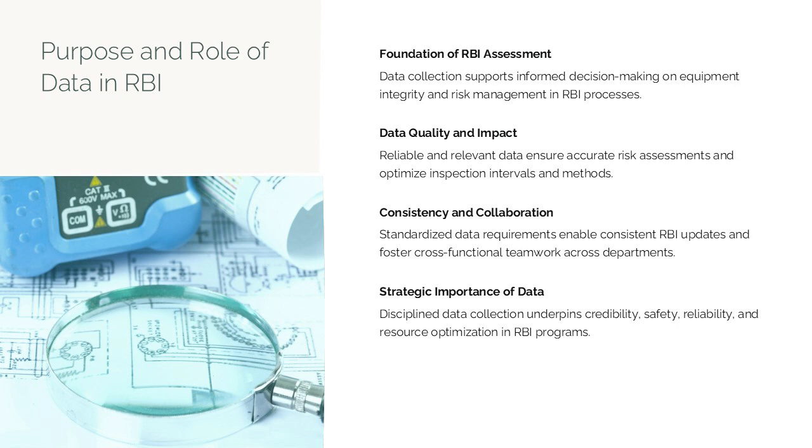In an RBI framework, data is not collected in isolation, rather, it directly supports the identification of credible damage mechanisms, potential failure modes, and realistic failure scenarios. These outcomes are critical inputs into subsequent RBI steps, including probability of failure, POF, consequence of failure, COF, and risk ranking. A well-structured data collection effort ensures alignment with the objectives, boundaries, and level of detail defined earlier in the